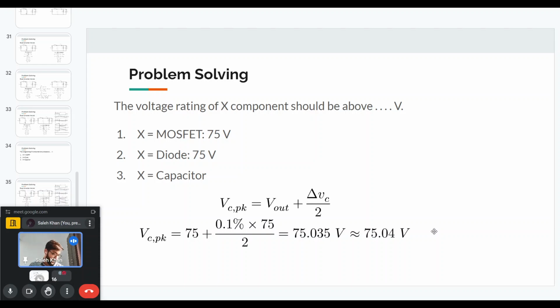So there's a question in the chat that in the boost converter, by default, the load is always connected to the source via inductor and diode when the converter is not supplied with the gate signals. How to avoid this situation? Yes, so the starting of the boost converter is a bit more complicated than the buck converter. Usually what people do is you can have another switch that connects the converter and the source, or you can have what is called a thermistor, which basically provides very high resistance when the temperature of this thermistor is low, and as it draws more current, the temperature rises and the resistance decreases. But basically, you will need some other circuit component if you want to avoid this condition.